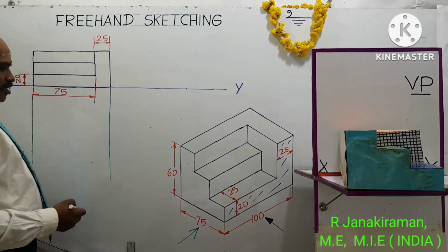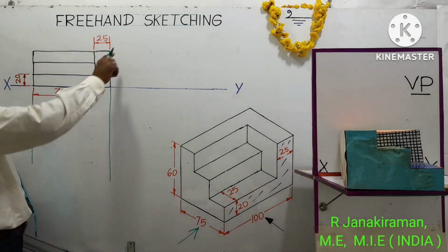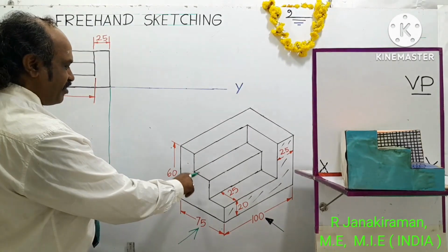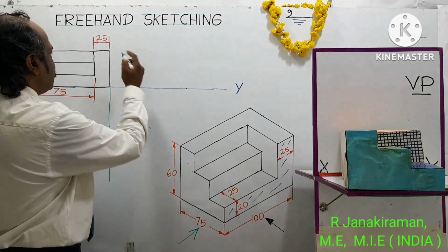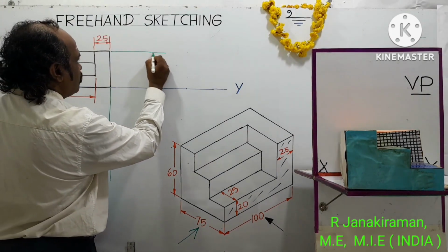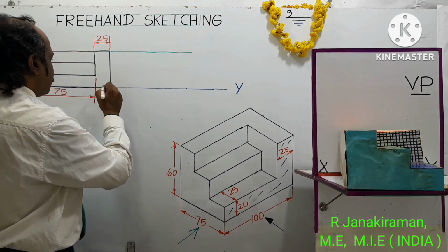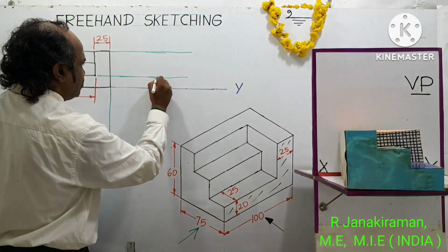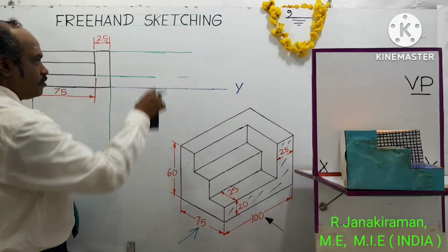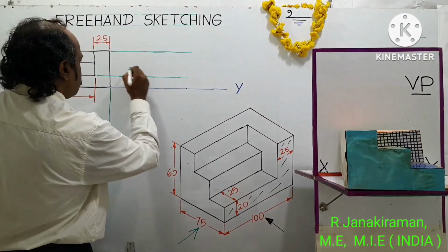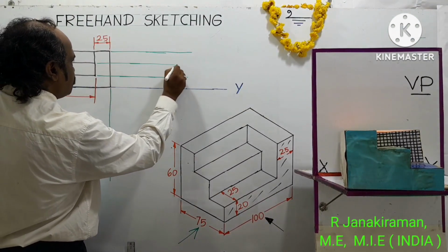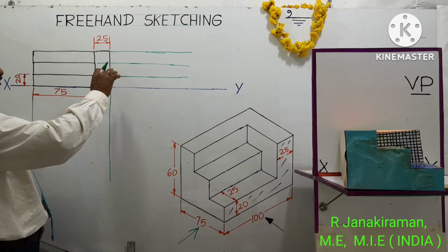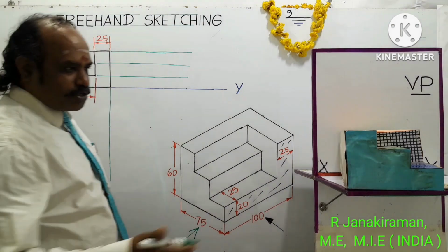Okay. And we will complete the left side view at first, before going to top view, because it is easy to project a top view from the side view. So draw horizontal projector from the previous front view. So step 1 height is 20 mm, that is projected using horizontal projection line using 2H pencil. Then step 2 height is also projected. Understand? So now we are going to draw a left side view on the right side of the front view, following first angle projection principle.